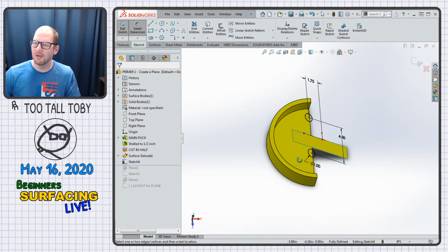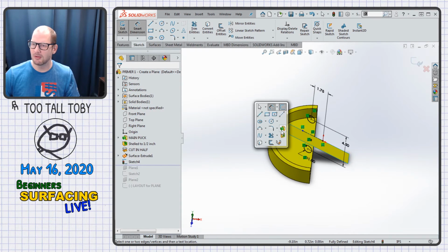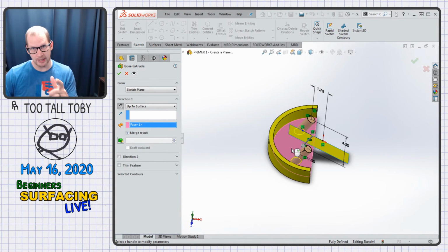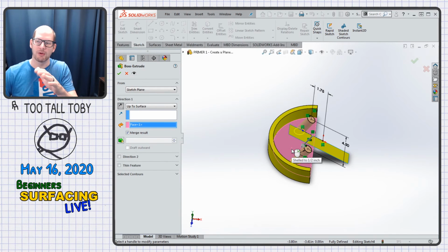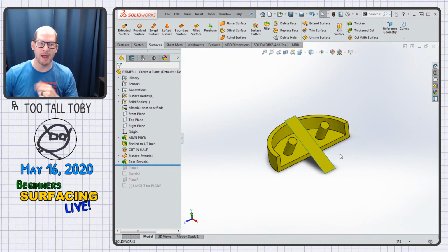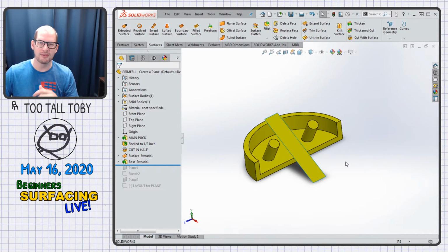All right, so now what I'm going to do is take that geometry and go to the extrude command, and then I'm going to double click on this face here, which is a shortcut to end my extrusion. Then I'm going to right click to finish that command. These are some of the shortcut videos that I've made in Power Moves. So if you want to learn some of these great time-saving tips, be sure to check out those Power Moves videos.